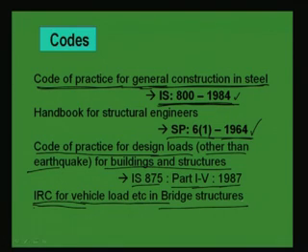And in the case of plate girders also, as we know, a plate girder is generally used for long spans. When the span of the beam becomes more than 18 or 20 meters and the load is very high, then we use a plate girder, and this is generally used for bridge structures. So there are some codal provisions in the Indian Road Congress code, and those things will be required.